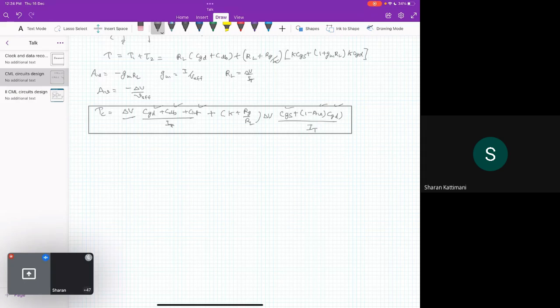Over different technology nodes, it was seen that a current density of 0.3 milliampere per micrometer works. Even if you go to a lower node, there is no improvement in gate delay. This is the Rg which is telling you about the gate delay, but this gate delay becomes constant after a certain point. So it is constant over technology node for gate delay.